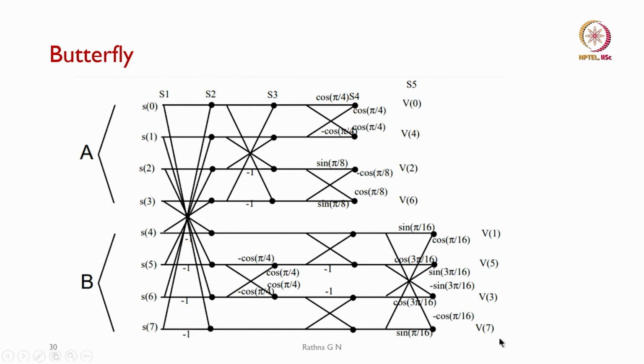original value. Later on we went on to use the butterfly structure to show that the order of multiplication for the 8 by 8 bit 1D DCT needs 64 multiplications and 63 additions, which can be reduced using the butterfly structures to 13 multiplications and then 27 additions. So, that is one of the techniques we used to show this. So, you will be seeing the cos and sine functions being used here.